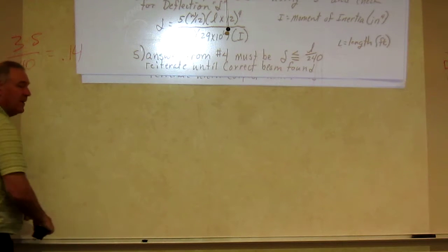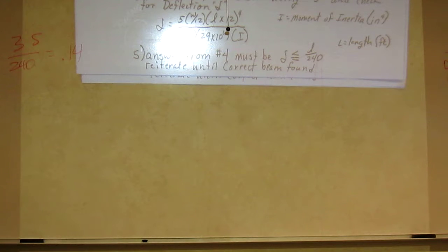Now, with that, why do we do deflection? Well, one, we don't want the beam to fail. Okay, but the deflection is really there, not that the beam's going to fail. You're going to kind of see through our calculations when I run that there's almost no way under normal conditions that this thing would fail. But we do get abnormal conditions. That's where they do fail. But the core to that 1/8 inch that we want it to deflect, that's going to keep the drywall from snapping and breaking underneath, pulling wires apart, plumbing, whatever goes through those areas. Okay, so we just want to minimize all of that havoc that can come from something moving too much.